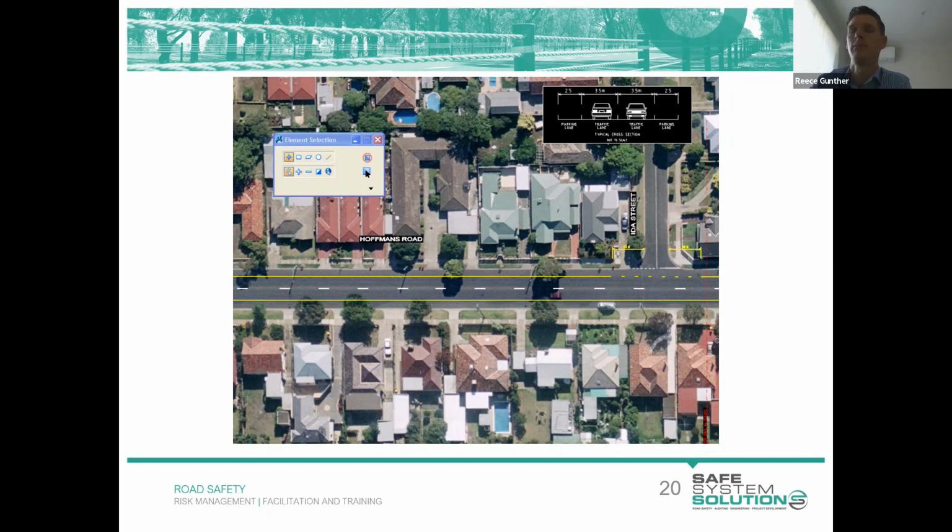So yeah, lane splitting, you can try and discourage it through enforcement or engineering treatments. Another way you can discourage it, if you've got large traffic lane width, is to hatch out or reduce the lane width and hatch out the shoulder area to try and discourage people from using that pavement, but also allow larger vehicles to track within that space if they need to.